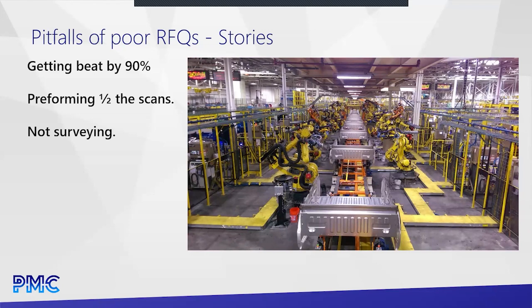It makes it cheaper if you don't have to do that secondary control. And exactly where that cutoff is is hard to nail down, right? Sometimes we can do 100,000 square feet without it and get usable data. But if we show up at an open warehouse that's 100,000 square feet, we can't do it. We have to do that secondary survey. And so exactly when that needs to be brought in and when that extra cost needs to be absorbed is something that comes through a lot of experience and understanding the site.